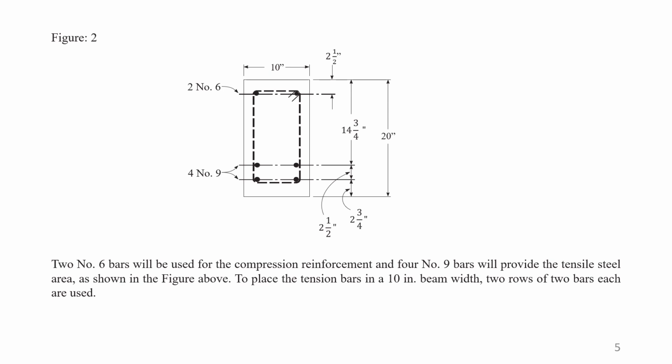That's why you must keep the spacer at least the size of the main bar or 1 inch, whichever is more. If the bar size is more, we keep that size of space, and if the bar size is smaller, we keep at least 1 inch or 1/3 of the maximum size of the coarse aggregate. These are the requirements for bar placing or bar arrangement.